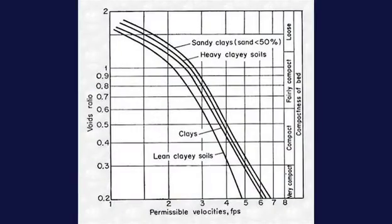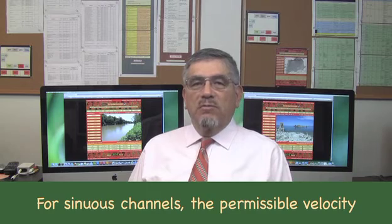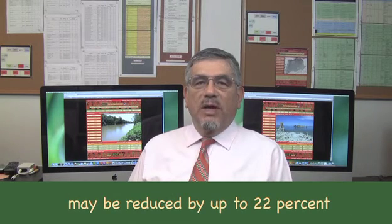For cohesive soils, permissible velocities vary with degree of compactness, from 1 foot per second for high voids ratio to 7 feet per second for low voids ratio, as shown here. For sinuous channels, the permissible velocity may be reduced by up to 22%.